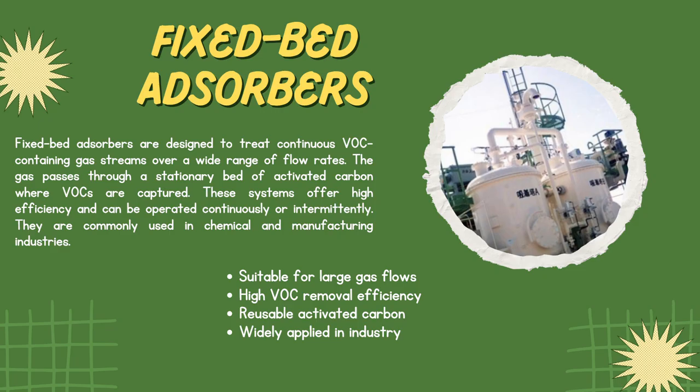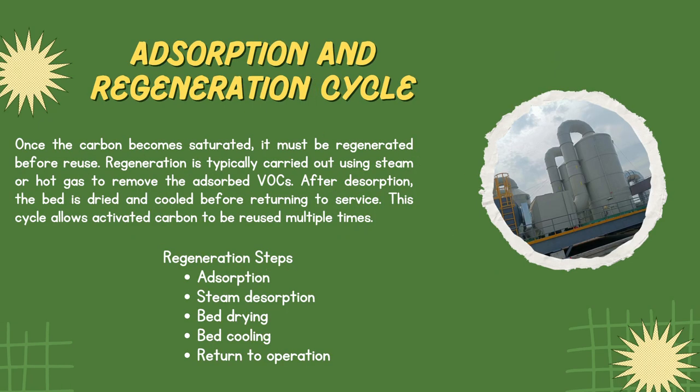Fixed bed adsorbers are designed to treat continuous VOC-containing gas streams over a wide range of flow rates. The gas passes through a stationary bed of activated carbon, where the VOCs are captured. These systems offer high efficiency and can be operated continuously or intermittently. They are commonly used in chemical and manufacturing industries.